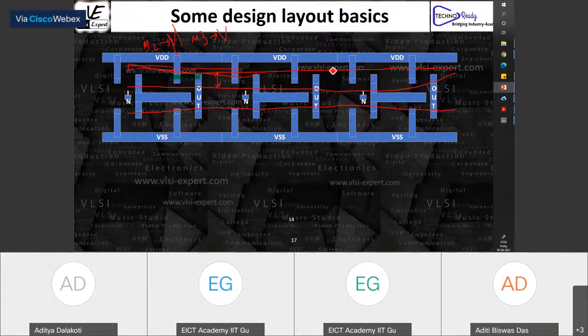So if you know your standard cell row track height, you are able to know how many M2 you are able to fit here. Similarly, based on your design width, you know how many M3 verticals you'll be able to fit like this. Because from the standard cell library, you will know what is the pitch you can have them at, and what is the minimum width you can have them at.